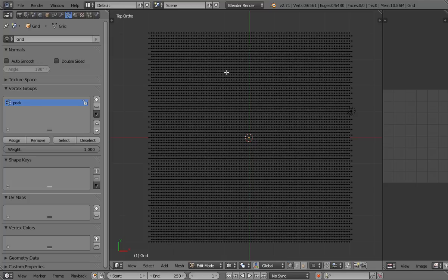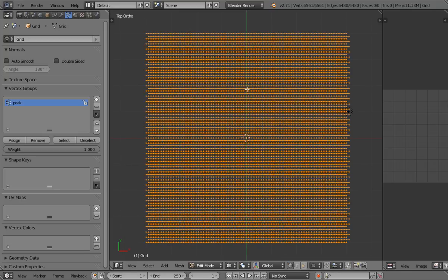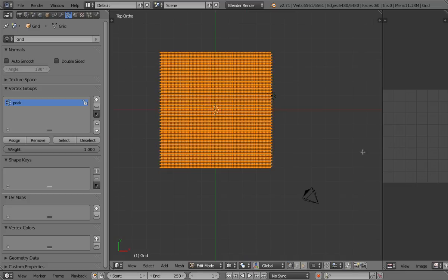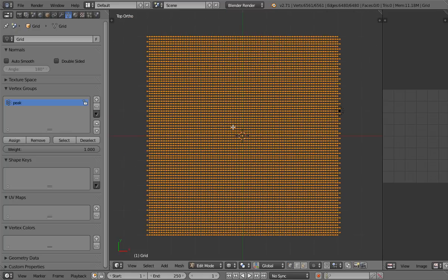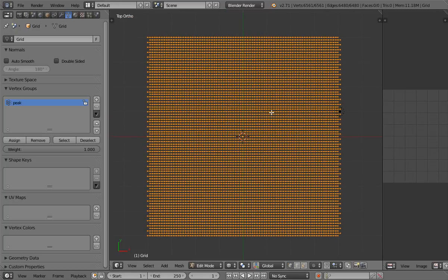Now let's create the vertical guidelines by duplicating all of these vertices and rotating them 90 degrees. So press the A key to select all the vertices, and now we're going to duplicate this and rotate this around the cursor in the center of the world. Now if the cursor is set anywhere else other than the center of the world, you can press Shift and C to recenter that. So now with all those vertices selected, let's change the pivot point in the header here from medium to 3D cursor to make sure we rotate this around the 3D cursor.